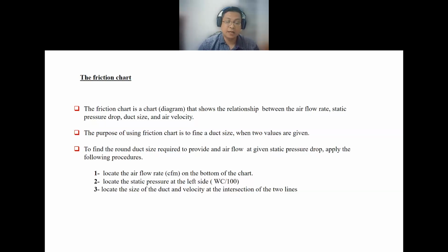We only use it because it is already good in testing, because it is already derived from research. It's not developed by only one person, but by certain researchers, and then we just use it to make designing easier. The purpose of using the friction chart is to find a duct size when two values are given.